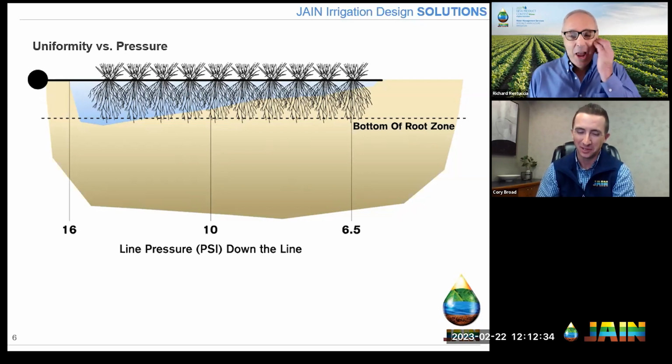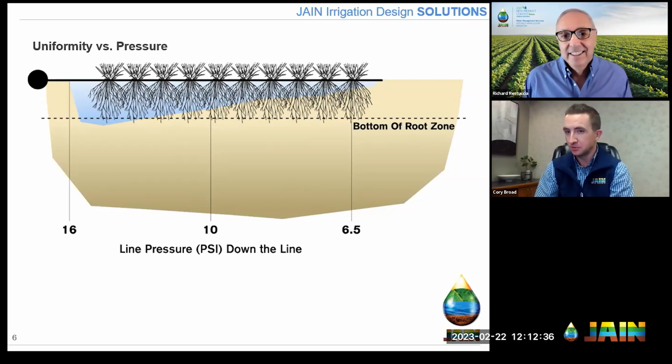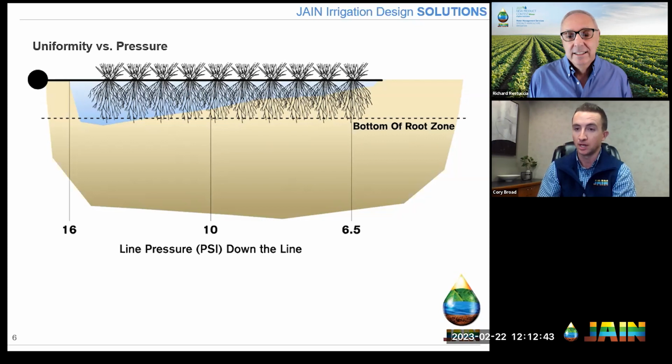And I said, well, we can run it farther if we use larger tubing because there's more area, there's less friction loss inside of it. I said, so that's one option, which to a certain extent, there's a terminal end. And then I said, the other option could be that we could run fewer sprinklers or try and change the flow rate of the sprinkler in order to lower the amount. So you just work through these things with them.